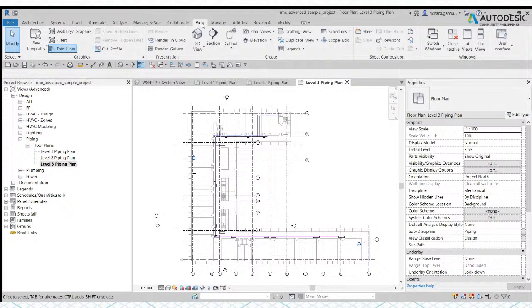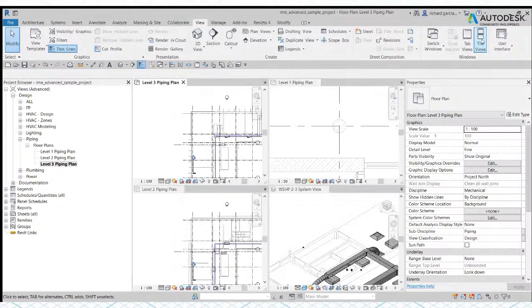and after that, you can go to the tile views, or you can just type WT. This is a very useful tool. Just click that one, and then it will show you all the views. And right now, they are not zoom extents. So what you do is you can right click and then select zoom to fit.